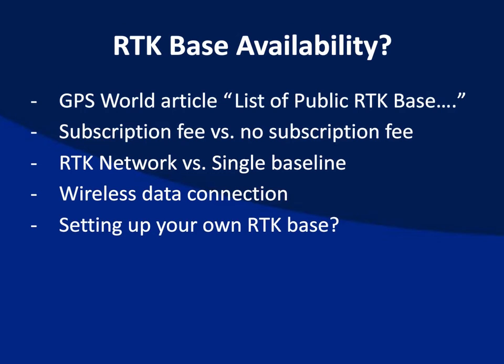I'll show you an example in a second. I've got some slides on that. There's RTK networks versus single baseline RTK, and I'll explain that in a second. Again, you need to have a wireless data connection, and it's typically done by internet connectivity via a mobile phone or a MiFi device or a SIM card or somewhere along those lines. And then lastly, if you don't have access to a public RTK base, how can you set up your own? And I'll give you an example of what I did earlier this year when there was a case like that out in the Midwest.